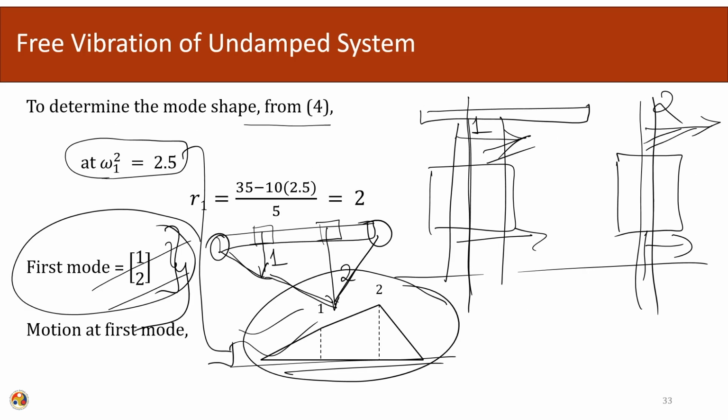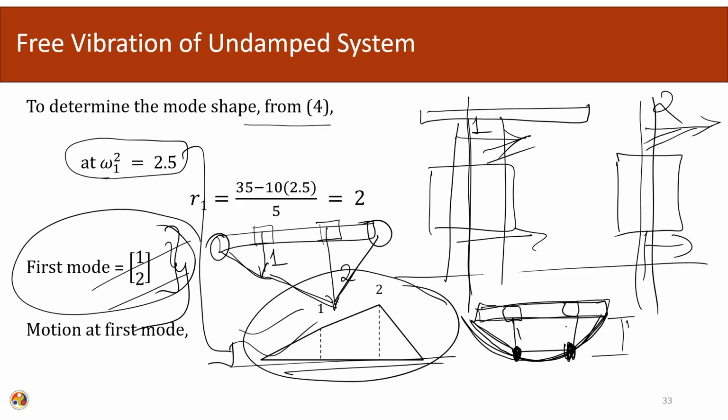Okay. So, this is intuitive also because we remember that if you have a uniformly distributed beam, if the distribution of the mass and stiffness is uniform across the section, then the section is going to behave like this. The actual continuous behavior will be a sinusoidal behavior, and this is the discrete behavior because we are assuming that the masses are concentrated at these 2 points. In this particular case this value will be the same, it will be 1 and 1 unit because the distribution of the mass and stiffness is uniform.